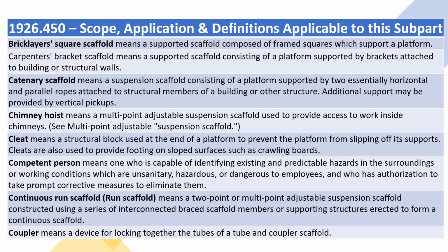Cleat means a structural block used at the end of a platform to prevent the platform from slipping off its supports. Cleats are also used to provide footing on sloped surfaces such as crawling boards. Competent person means one who is capable of identifying existing and predictable hazards in the surroundings or working conditions which are unsanitary, hazardous, or dangerous to employees, and who has authorization to take prompt corrective measures to eliminate them.